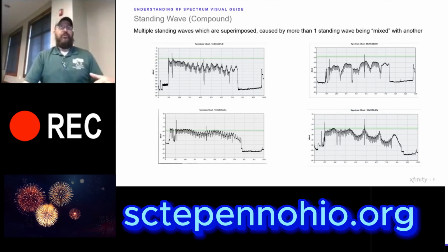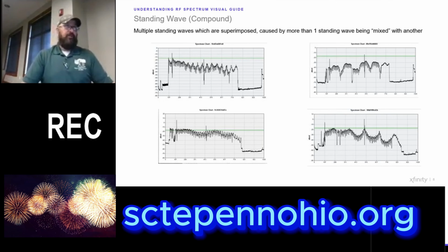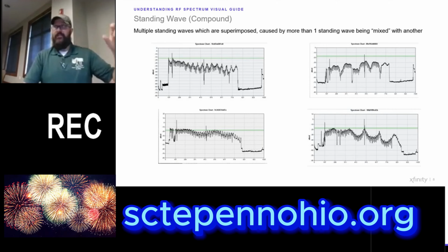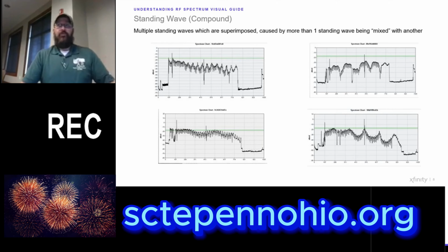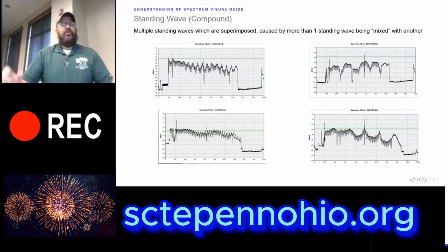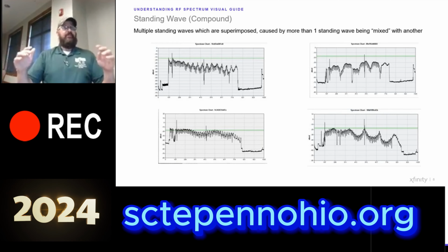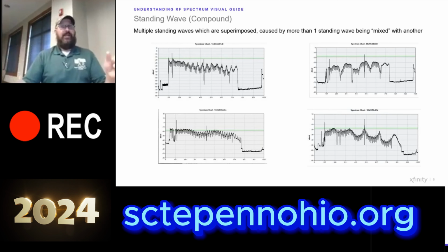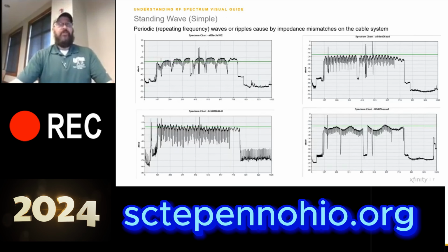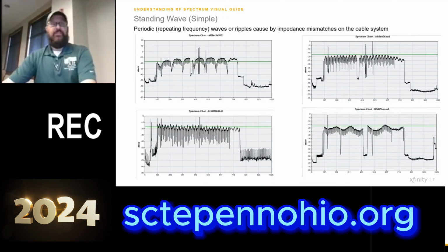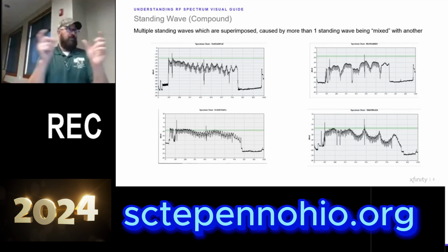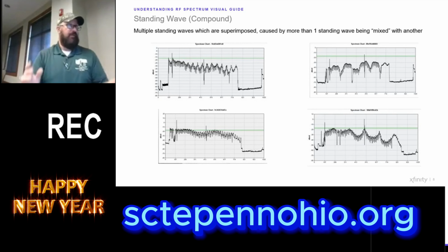Now you can throw other things in there and put some water in that cable that got in through the radial crack and settled in the cable and created attenuation nulls that will identify as what we call water waves. So these are standing waves that are not periodic or purely periodic like the previous ones that we looked at, right? So the peak-to-peak differences are products of your multiple reflective cavities and the energy being bounced back and forth.